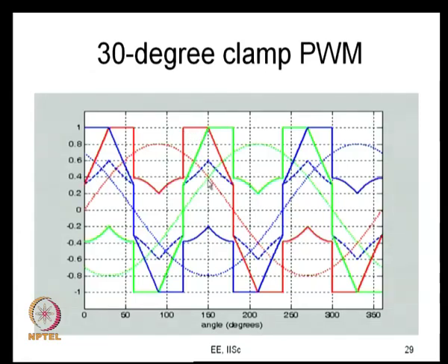In the middle, you are still following the positive common mode component. The positive common mode component now basically comes from here. The positive common mode component is the difference between Vp and this signal, and so the next phase, Y phase, gets clamped for 30 degrees now. So here, R phase is clamped to the positive bus for 30 degrees, and here again for 30 degrees. This is between angle 30 to 60 degrees and this is between angle 120 to 150 degrees.